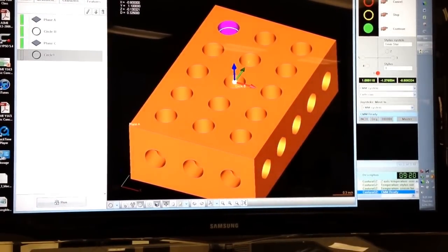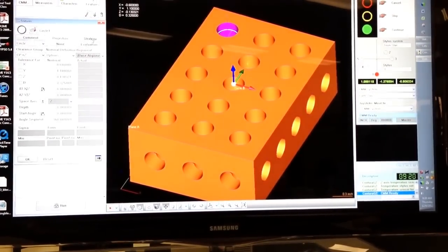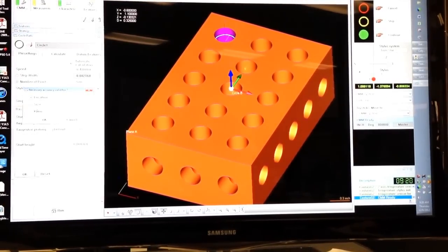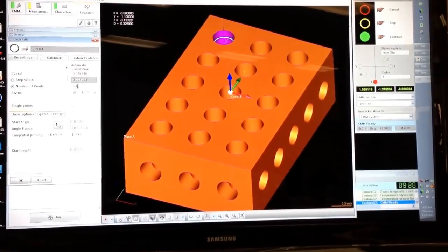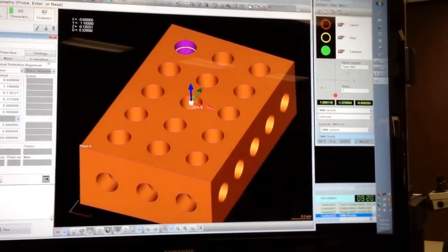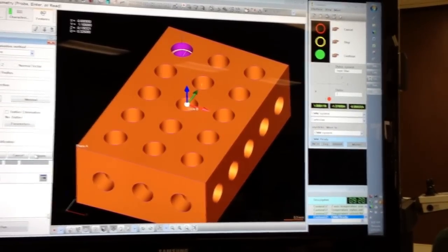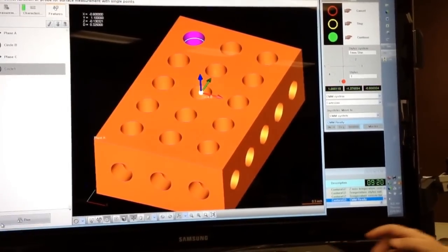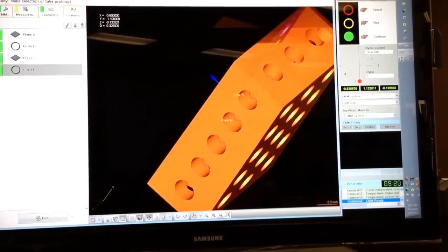The first thing is we're going to open the circle up, go to the strategy, go and open the circle path, and hit the Calculate button, choose Form, and allow the machine to choose an appropriate speed and number of points for this measurement. I then click OK, OK. When we scan, we filter. When we filter, the default setting is always correct. We apply the filter. And now I press F9 to execute that feature now and test run it. You see that the machine has test ran the feature.